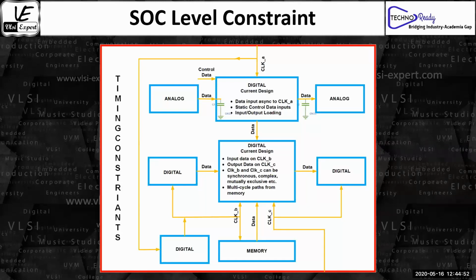Okay, so synchronous usually means the clock source is the same. I think Tilak was already mentioning this. Again, I might be oversimplifying a few things, and we can get into it in more detail. But to begin with, very simply, think you are being supplied from the same clock, but your frequency is different. For example, think of clock A on the top as a 1 gigahertz clock coming from the source, which is the same as the clock C source, but clock C is running at 500 megahertz. Clock A repeats itself after every 1 nanosecond, but clock C's period is 2 nanoseconds. They are both synchronous to each other, but there might be some delay which is different between clock A and clock C. Reaching different digital design blocks, there is a clock delay associated with them, which is different.